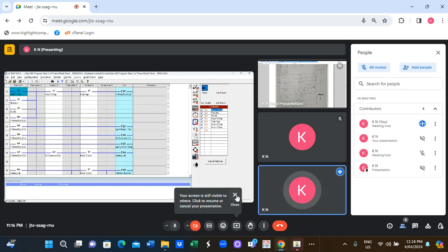Here are the inputs: I1, I2, I3, I4, I7. Those are inputs. Outputs are Q1, Q2, Q3, Q4. I1, I2, I3, I4 are inputs, Q1, Q2, Q3, Q4 are outputs. The auxiliary contacts are N1, N2, N3, N4, auxiliary contacts inside the devices. What we need to do is connect only the input and the output. The rest are all in the set. So now we make the simulation with the PC.